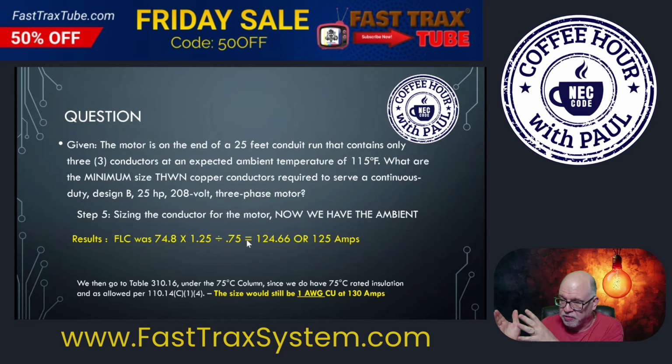And I can show you that. Let's just say it was 80%. So I go 74.8 multiplied by 1.25 equals 93.5, divided by 0.75 equals 124.16, divided by 0.80 is 155, and we would have had to find a conductor that's good for 155 amps. Then after the adjustment and correction, we would have been making sure that we had a conductor that was again at least 125% of the FLC of the motor.